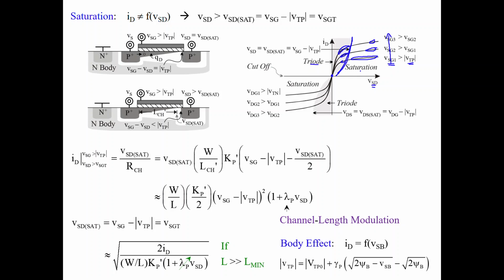Now, interestingly, if you look at the structure of this device, we can apply the ground to the right-hand side and a negative voltage to the gate and a negative voltage to the left-hand side. What we see here, all the voltages are reversed, but since the device is symmetrical, everything will work the same way, but in the opposite direction.